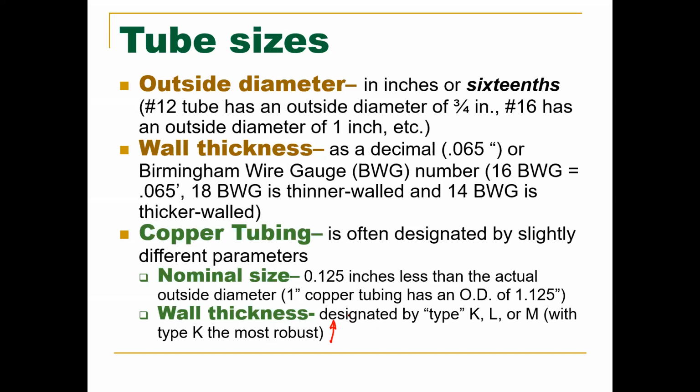I told this story to the other class because they got a little bit farther ahead of you guys, but I just replaced the water line to a hose spigot in my garage. I had to use 1/2 inch K-type piping because it's in the garage, it's exposed. One, it'll have a higher chance of not freezing and busting a pipe open if we forget to turn the water off, because a thicker wall can stand up to a little bit more pressure. And two, it's a garage. We hang a lot of stuff in there, and a lot of that stuff can bang into it and dent it and cause problems and weakness. So we had to go with the type K. Knowing that is important as well.